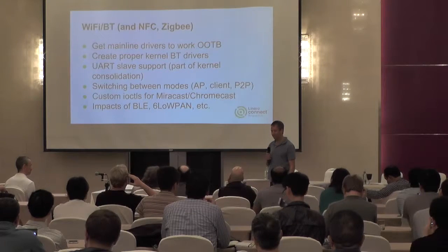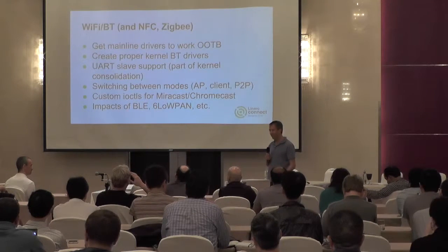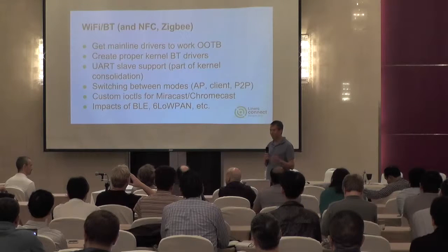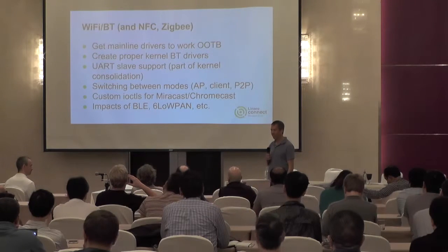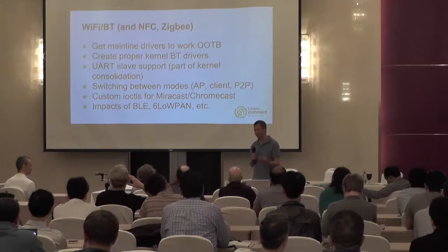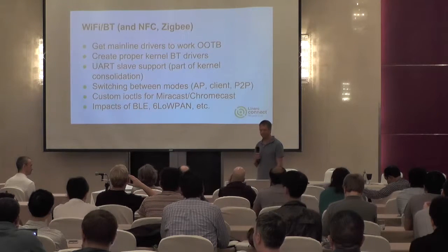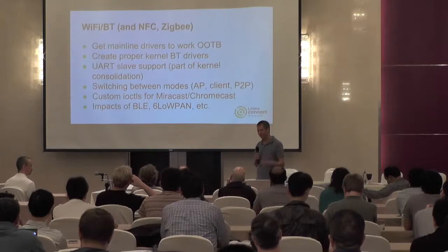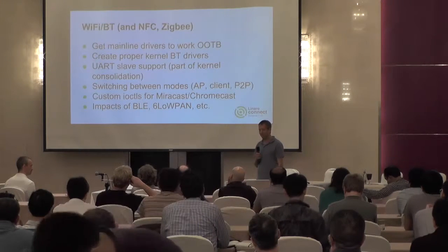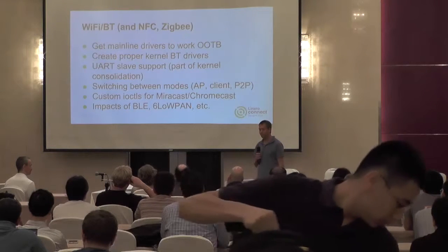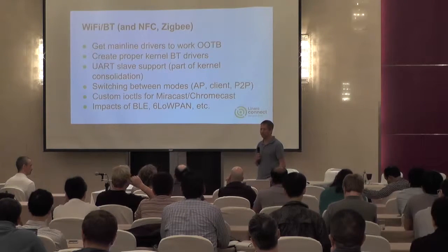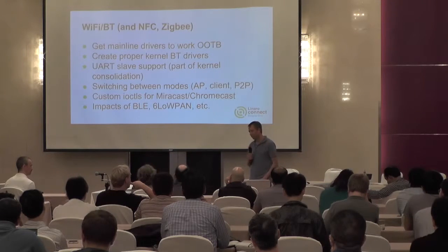What exists today for UART attached Bluetooth devices is kind of either not addressed or hacked in how you handle interfaces other than the UART itself. When you have Bluetooth devices soldered down on your board, you also have regulators to control GPIOs, control resets, that kind of thing. There's not really a defined way to handle all those extra bits with Bluetooth. There have been patches for years.